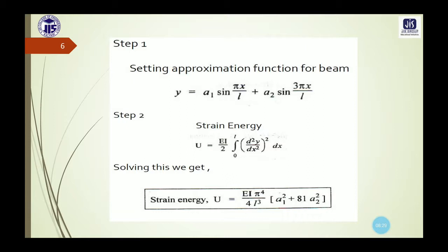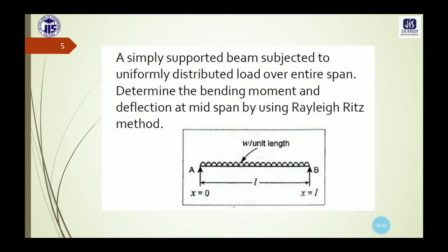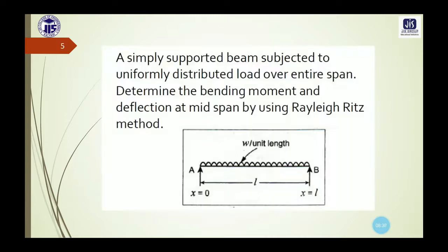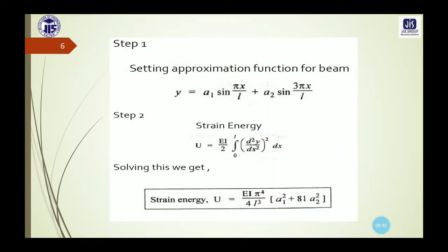Next, we need to determine the strain energy, that is capital U. The formula for the strain energy U is EI divided by 2, integration 0 to L, (d2y/dx2) whole square dx.